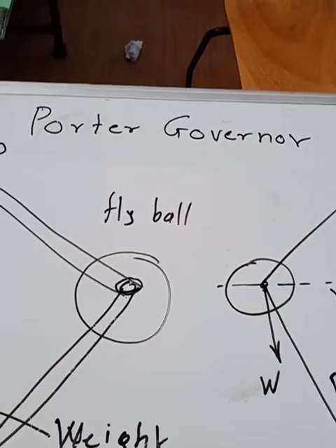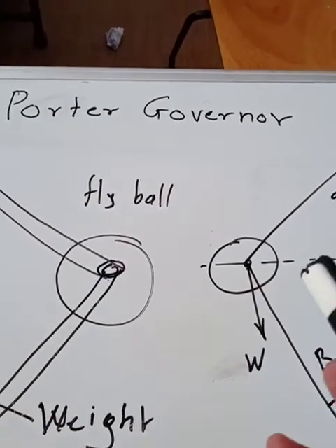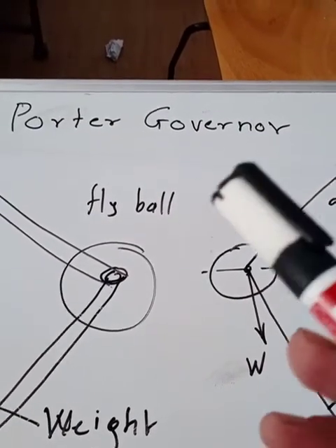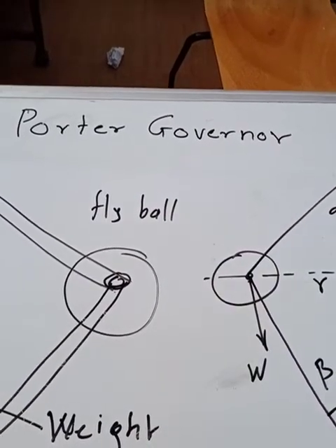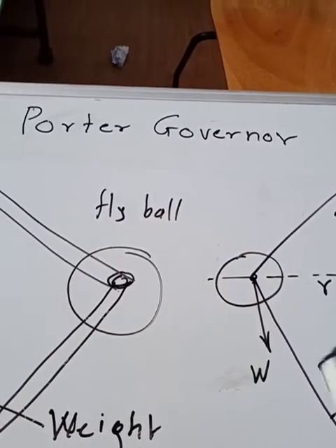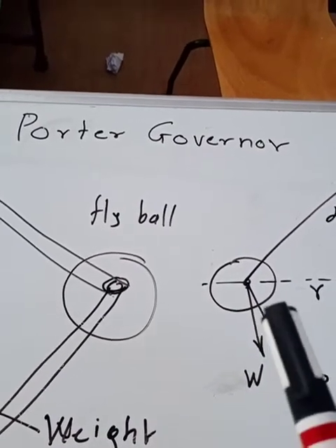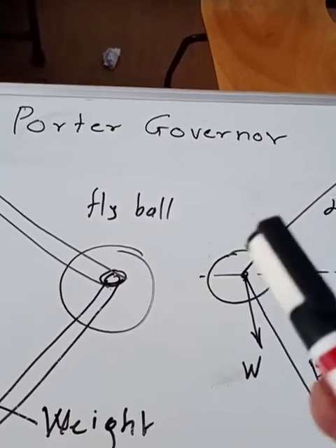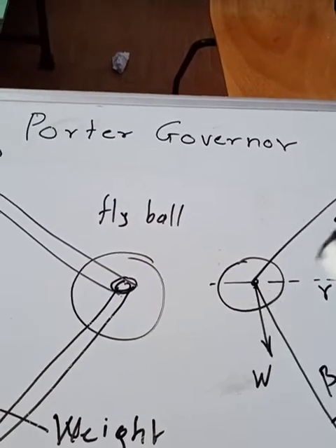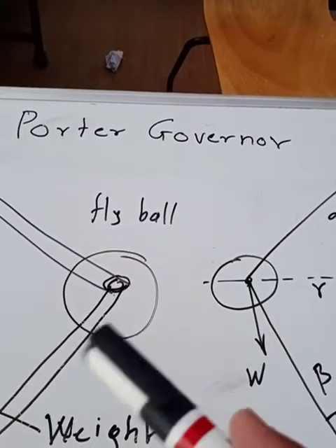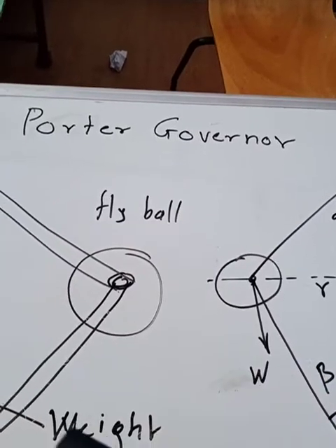Already we have seen the types of governor and why governors are used, how the governor is going to work, and what the various terms are which are used in that governor. We have seen a simple type of governor, that is the Watt governor. Now we have seen the limitations of the Watt governor also. That is, the Watt governor beyond 80 to 90 RPM is going to become insensitive. That's why the next versions of governors were generated or found out.